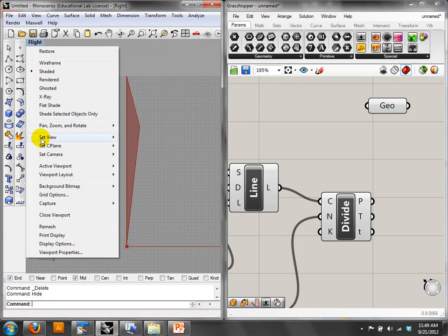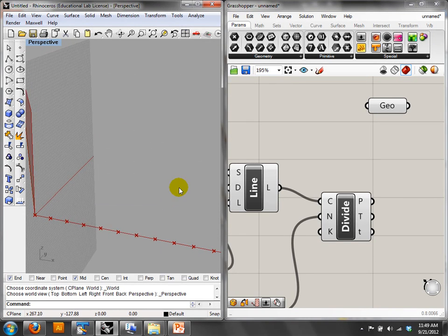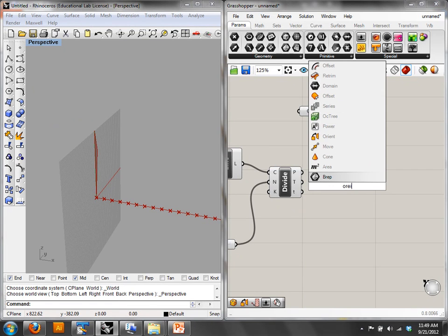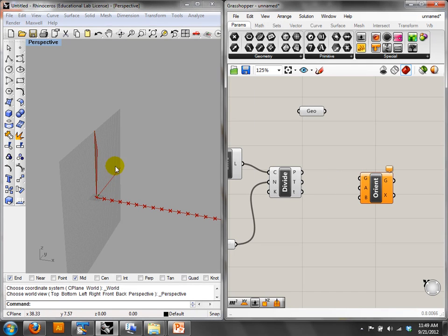So I had these fins that I made. And using Orient, I can distribute them all on this line. Because again, this is not parametric, it's just some reference object. So I don't have anything I can plug into it to change its location. I could move it, but that doesn't pay attention to these points. So Orient is really the tool for the job.